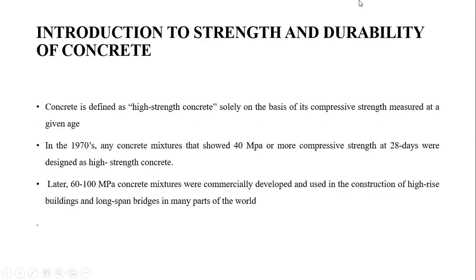So first we are going into the introduction of this chapter, that is, introduction to strength and durability of concrete. Here concrete is defined as high strength concrete on the basis of compressive strength measured at a given age. So when you go for concrete, it can be determined only by its high strength. In the 1970s, any type of concrete which shows about 40 MPa, that is megapascal,